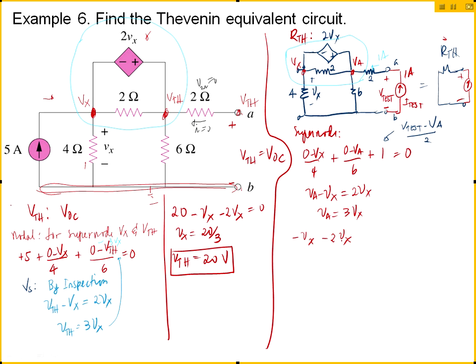Am I doing this correctly? You have to watch my algebra. What will be the last term? Plus 4 equals 0. Anybody with a complaint? The 4 came from 1 times the LCD. The LCD was 4. So I'm going to get a Vx that is 4 over 3. But that means that the VA is 4 volts. Okay? Are we really solving for VA? What are we solving for? V test.